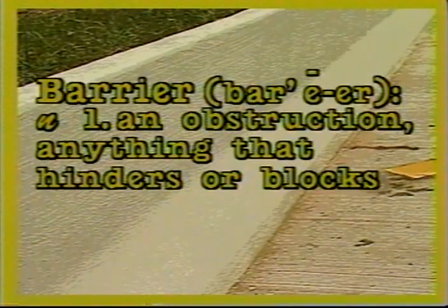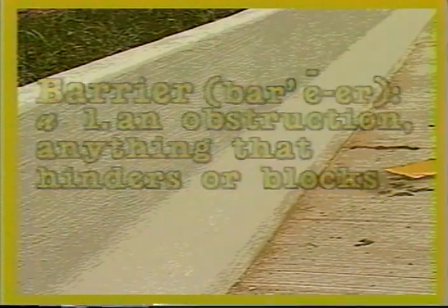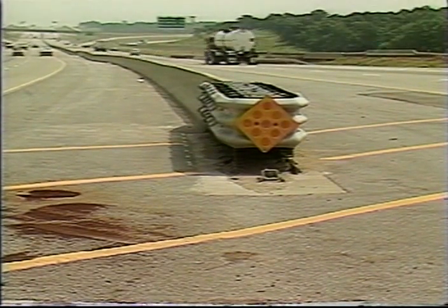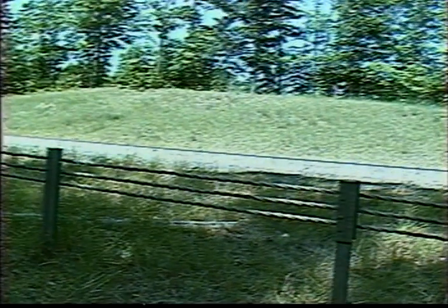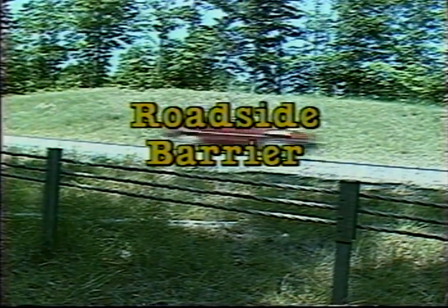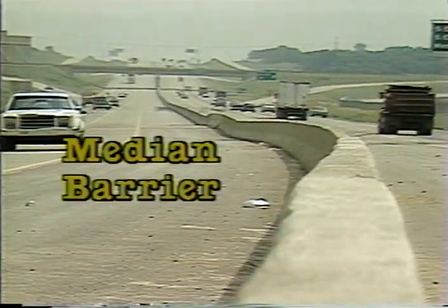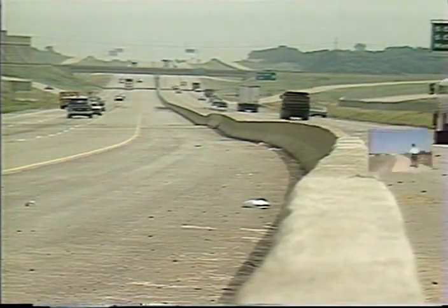Webster's dictionary defines a barrier as an obstruction, anything that hinders or blocks. Basically, that's what we expect traffic barriers to do, to block or prevent a vehicle from running into a more hazardous object. In a government manual commonly known as the AASHTO Barrier Guide, definitions of the 3 basic types of traffic barriers are given. A roadside barrier offers protection from one side only and applies to roadside hazards. A median barrier gives protection from both sides and applies to the separation of opposing traffic.